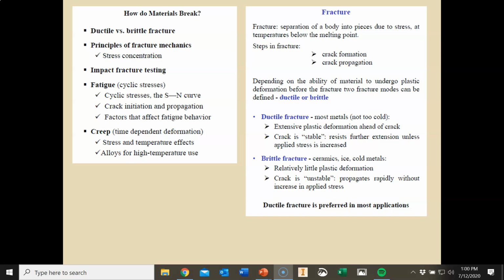Ductile materials exhibit massive amounts of plastic buckling or deformation in comparison to brittle materials. In ductile fracture, the crack grows at a slow pace and is accompanied by a great deal of plastic deformation. In this case, the crack does not expand except when high levels of stress are present. Under a microscope, the surfaces of materials with ductile fractures appear irregular and rough and exhibit some dimpling.